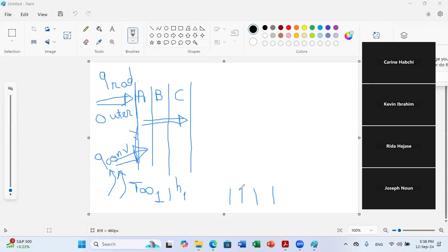And as we said in this course, we'll try to compromise between energy efficiency and cost. That's why we'll do an economical analysis for the project and alternatives that we are suggesting. So in moderate climate, you can compromise a little bit the quality of your envelope. You can have lower resistance for your envelope because you don't have very large variation in temperature between inner and outer space. So this will allow you to reduce the cost of the material you are using in your envelope.